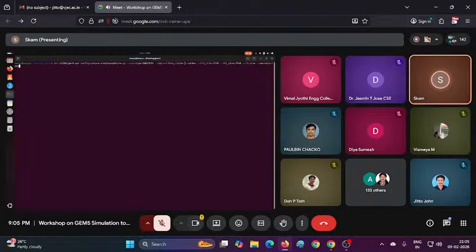If you want, you can specify the cache sizes, like the L1D cache size and L1I cache size which you want, and the maximum number of instructions to be run. Here, I have given the maximum number of instructions as 3. Okay, so I have an input which is called uniform random. I'll show you what this uniform random is.